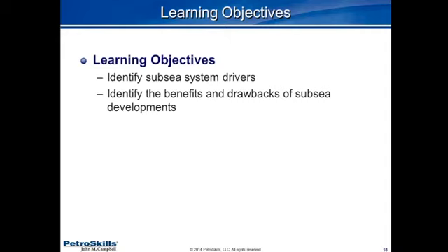As we've seen, some of those key drivers include the reservoir distribution and the reservoir size, so widely spaced reservoirs and small reservoirs make subsea more attractive because it can bring those reservoirs back to a facility which is shared with other developments, possibly subsea or DVA as well, and can also be used to tie back distant reservoirs to existing infrastructure, thus reducing the overall cost of producing those reserves and improving the economics of these fields.